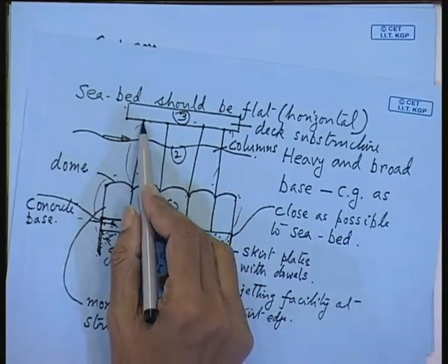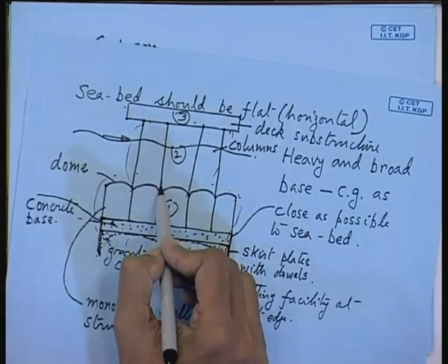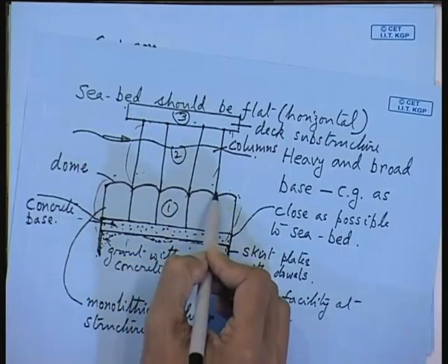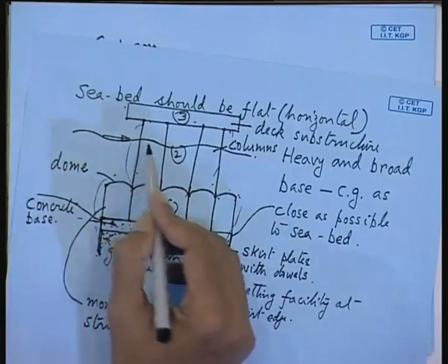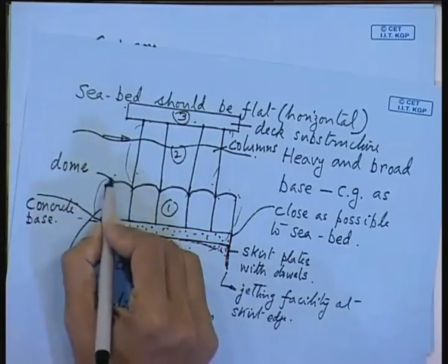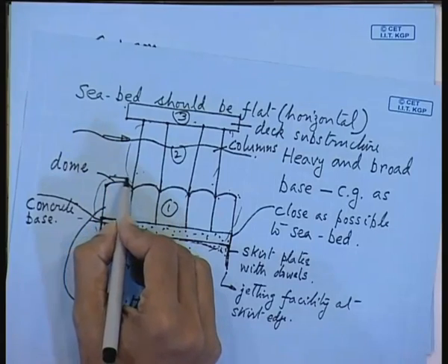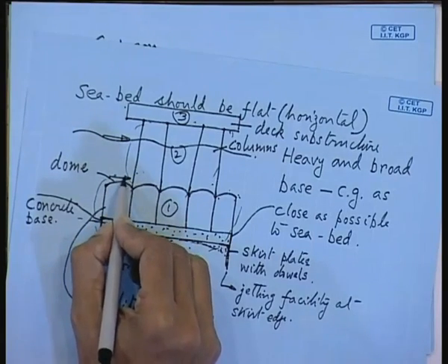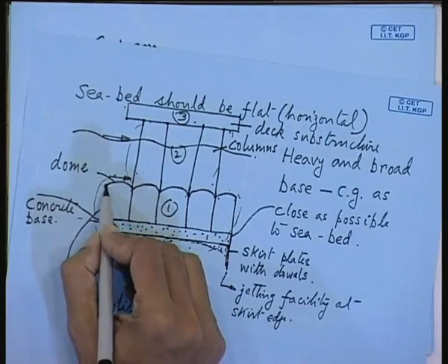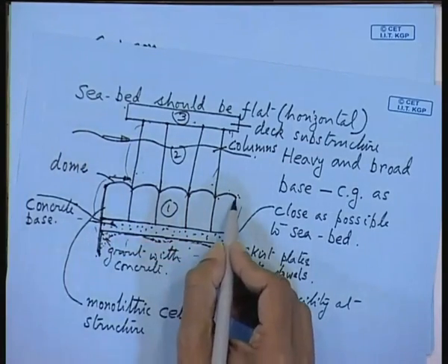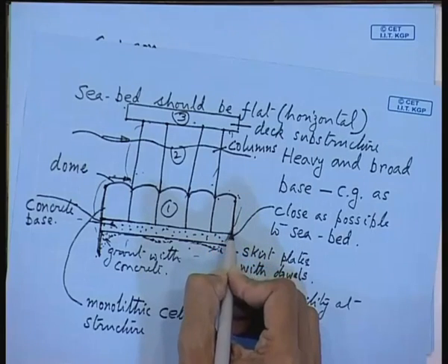So the bending load that is coming will be taken up by these columns, and not only this, down below you have hydrostatic pressure. The hydrostatic pressure will be quite large because of that rho g h formula. H is quite large at the base of the caisson.